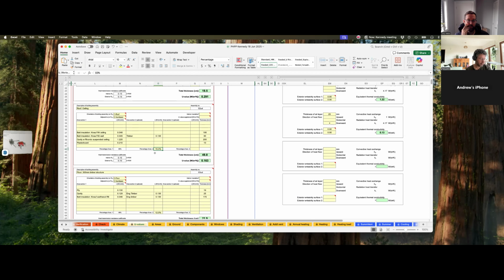Can you use like the foam stuff? No, we generally use a number of products on the market. ProClimate have put out products designed to do this. So basically each circuit will have a penetration. If you've got 5 circuits, you'll have 5 penetrations. And you can potentially bring them through in the one spot, although probably best practice not to do that. But these are the sort of things I've got to thrash out now because I've got to design my circuitry for going upstairs and through the house. I've got to know these things.